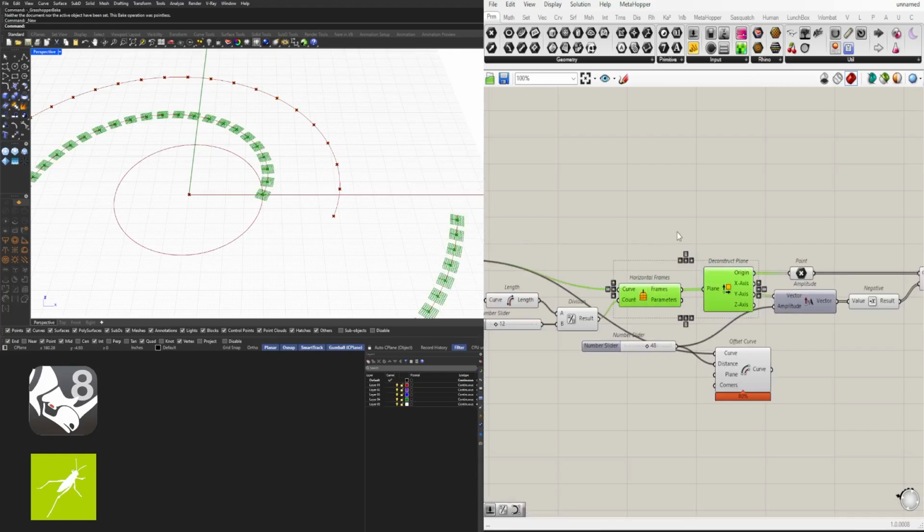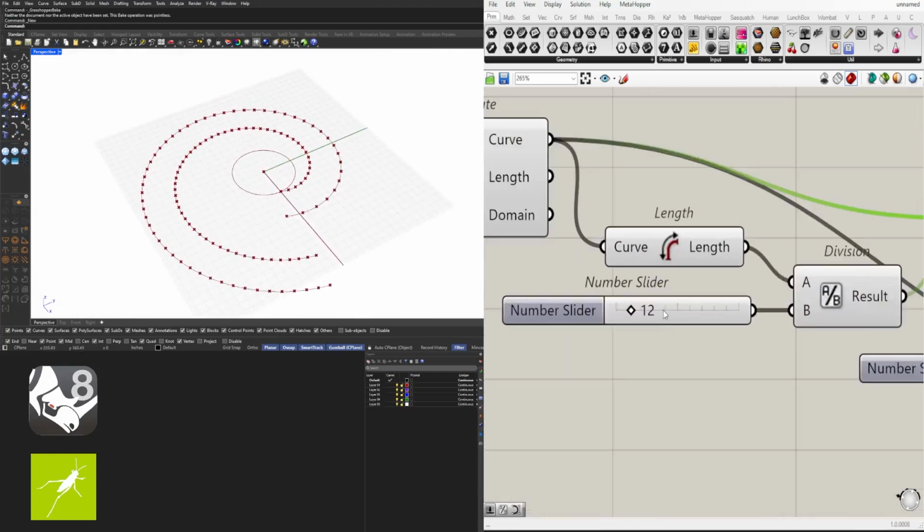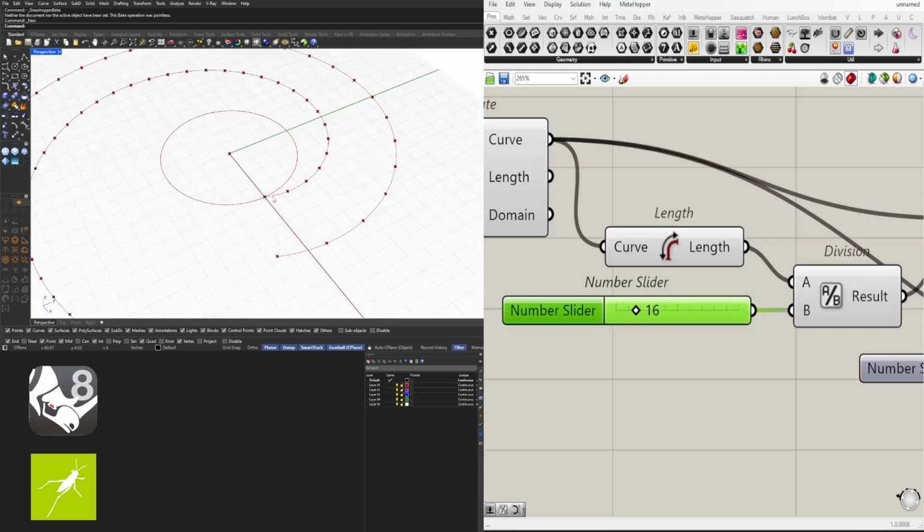So now we can hide all of the reference frames. And notice that now we can increase the tread size, and it's going to give us the minimum, and it's going to get larger as it comes out here, which means that this could even get smaller, right? Because where it's actually critical for you to have a large number is in the middle. So let's keep it at 12 here.